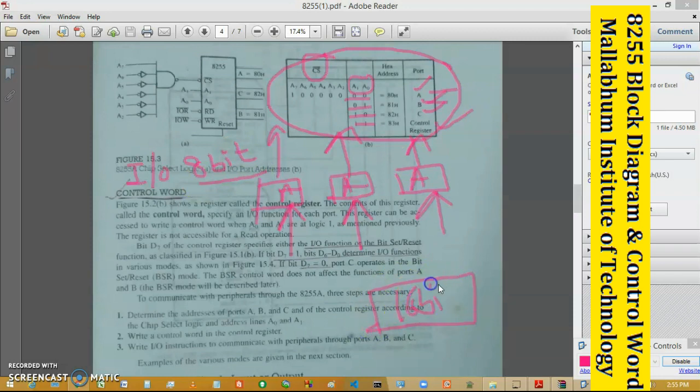So that's why we don't need A0 to A15 addresses. We only need A0 to A7 for identification of any 8-bit port. So that's why here we use only A0 to A7. Now A0 and A1 are responsible for selecting the different ports. The rest of these are to be connected with the 8255 so that all together they can select the chip.